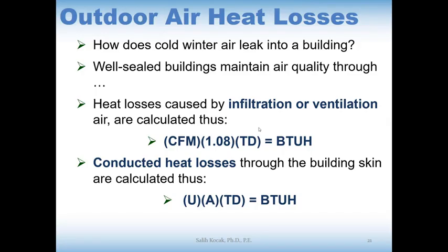And let's say that we have a 12,000 square foot roof, and its U value is 0.15, which is better for you to just follow it up. So U value is 0.15 and the area is 12,000 square foot. This is our roof. And if indoor temperature is 70 degrees and the outside temperature is 10 degrees, what's gonna be the heat loss here in terms of BTUs?